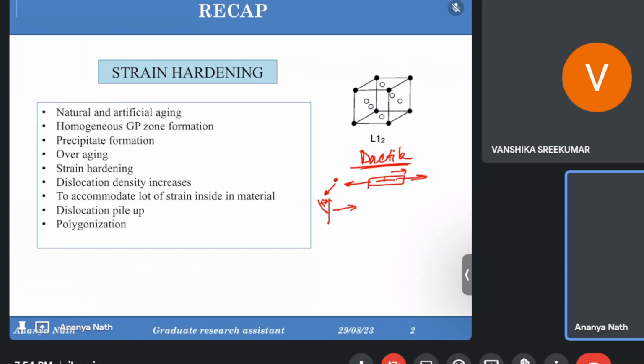So there it will get attached again. It will act like one dislocation again, and it can move easily again. It will give rise to the ductility property. But if the stacking fault width is more, the solute atom will sit and the strengthening will take place.